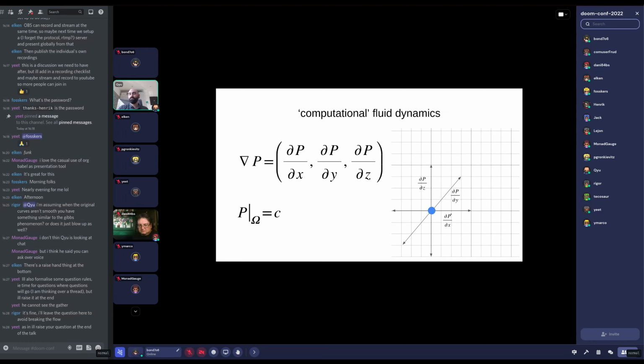And this now gives us a new set of problems to deal with. Before, we just had to take time and split time into little chunks in that kind of linear way, pretty straightforward. But now we need to take this pressure and discretize this into different directions. And this is where the concept of elements comes in, and why whenever you see stuff in CFD, you normally see it done on a computational grid. The concept of grid is because we need to now take the quantities that we have, the velocity, the pressure, and actually spread them around in space.